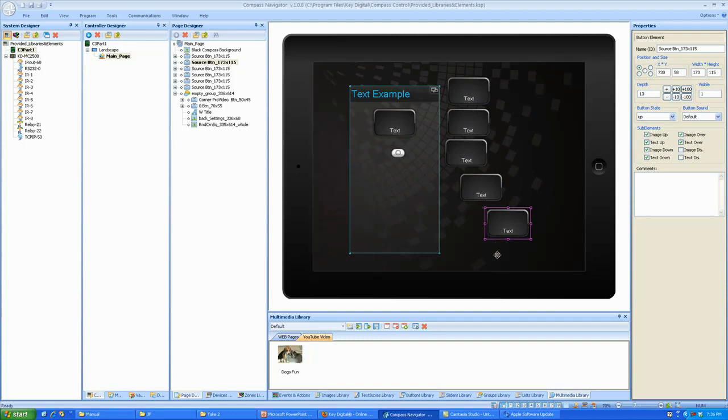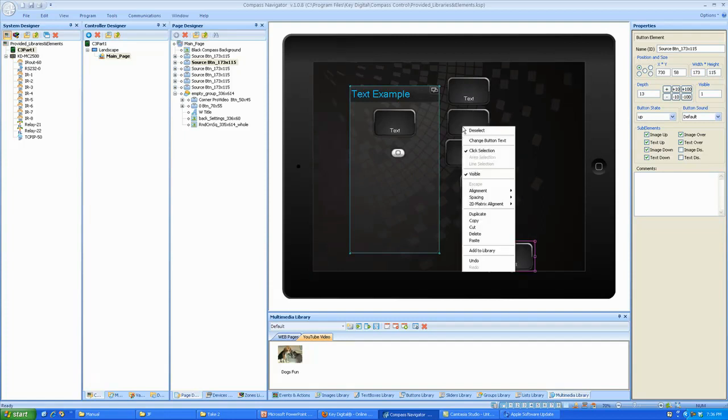We can view all of these by right-clicking, and we can see alignment options and spacing options. Let's start with our alignment options. You have two options that are most commonly used, the horizontal center and vertical center, where we take the center of each of the elements that we'll be aligning, and we can align them based on that center, either horizontally or vertically. Those are accessed with quick shortcuts, F5 or F6.